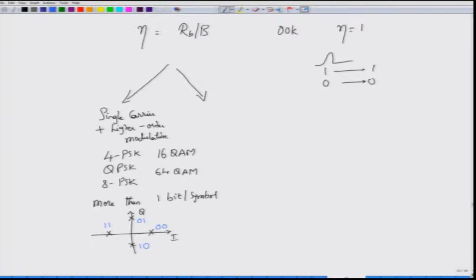When you transmit phase 0, you are actually encoding that phase 0 by 2 bits. In other words, if you want to transmit the 2 bit sequence 0 0, you transmit a signal which is say cos omega st, where omega s is the signal frequency, plus 0 degrees. If you want to transmit 0 1, so you group 0 and 1 into a bit sequence, then you transmit cos omega st, but this time shift the phase by 90 degrees. Similarly, you can fill up for the remaining 2.